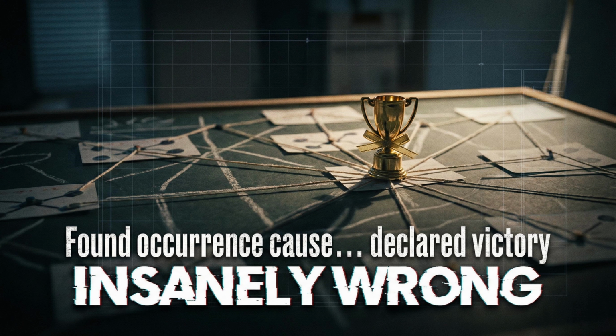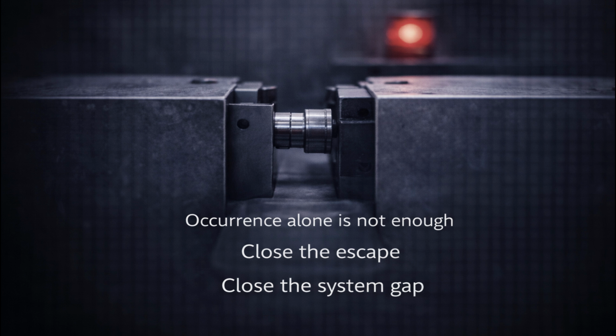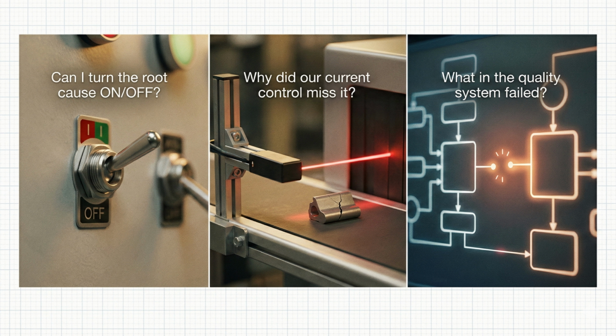Many teams declare victory after finding the occurrence cause. This is insanely wrong. In D4, you must work 3 separate legs: the occurrence, why it happened; the escape, why it wasn't caught; and why the quality system allowed it. Find occurrence only, and the same kind of defect will leak again if you don't close the escape or the system gap. Keep D4 sharp with 3 questions.